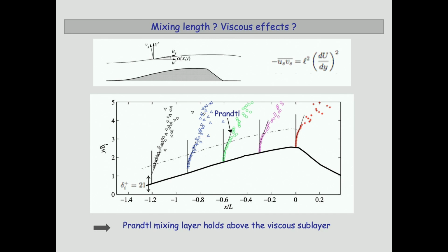So from these two measurements, we can deduce the length L and check the Prandtl mixing length model, and check that it gives good results, with here a viscous layer where there are no turbulent stresses, and delta y is the distance from the bed which separates an outer region, where stresses are unimportant, and an inner layer where these stresses are important. But I cannot go further.